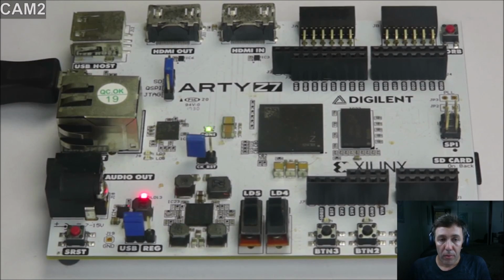This is due to relatively tight timing requirements of the video signal. Those requirements are heavily dependent on the chosen resolution, color depth, and refresh rate. But in any case, this is not an easy task even for such a high-performance multi-core SoC, which we are going to use today. Even an ARM core running at 600 MHz is not going to tackle the job. This is why we have to leverage the use of FPGA or PL side to achieve our end result.